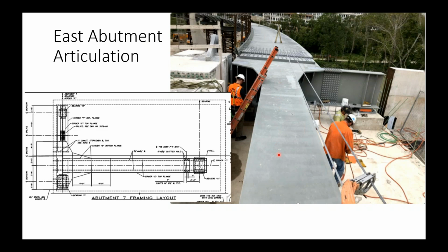The other thing that made this a little bit more challenging was that this is a 760-foot long bridge altogether, and we didn't want to lock in the temperature effects. So as the bridge heats and cools, the expansion joint here at this location, we wanted to make sure it was allowed to move. So these are sliding bearings.